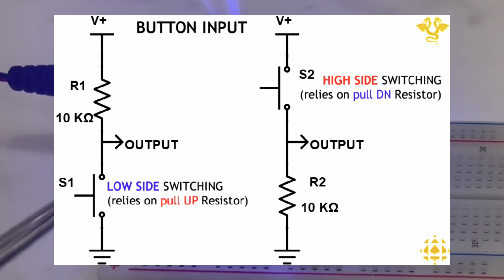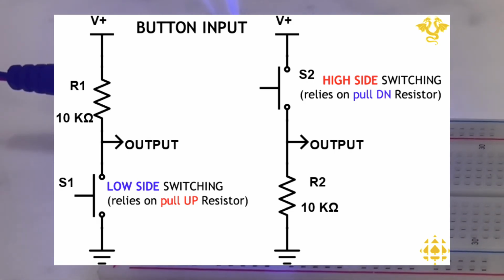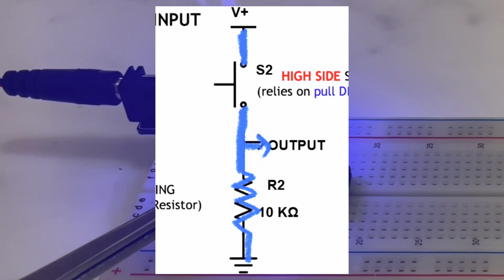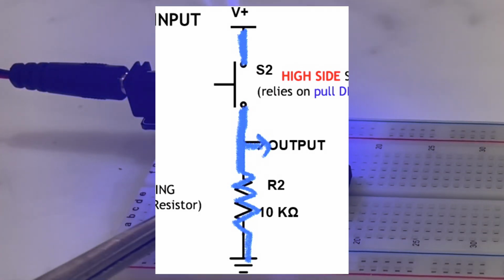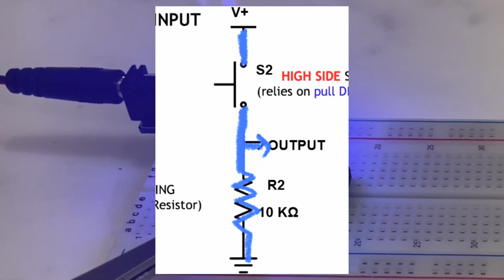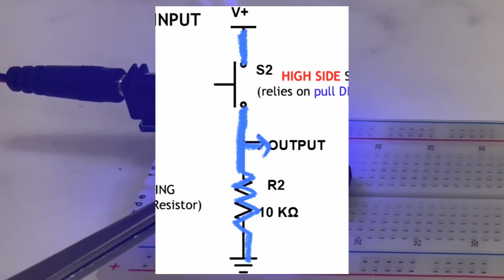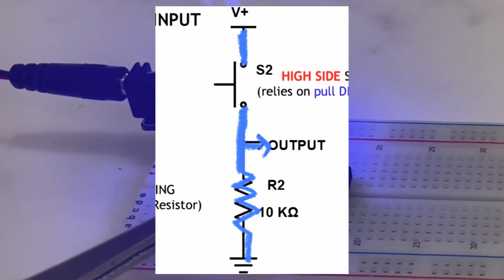The circuit relies on the momentary PBNO, as without it, the circuit is closed. Once this button is pressed, the current will flow and split at the junction point. Part of the current will reach and pass through the output, while the other part of it will travel through the second 10 kilo ohm resistor.